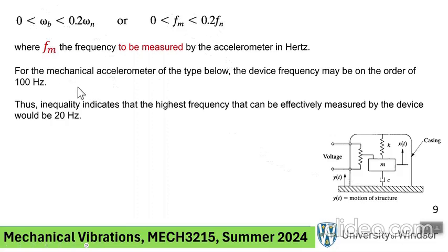Okay. So generally speaking, old-fashioned accelerometers like that are defunct, but they're very good for explaining things in terms of what you have learned in the last 3-4 weeks. The natural frequency of a gadget like this as an accelerometer is around 100 hertz. If I put 100 hertz here for Fn, I get the frequency of the base motion, meaning the thing that you mount the accelerometer on and you want to see the motion of.